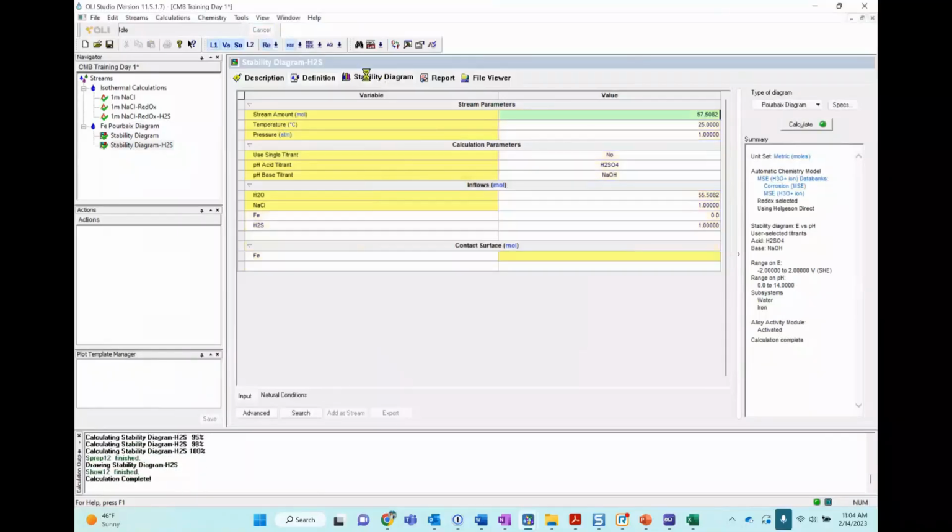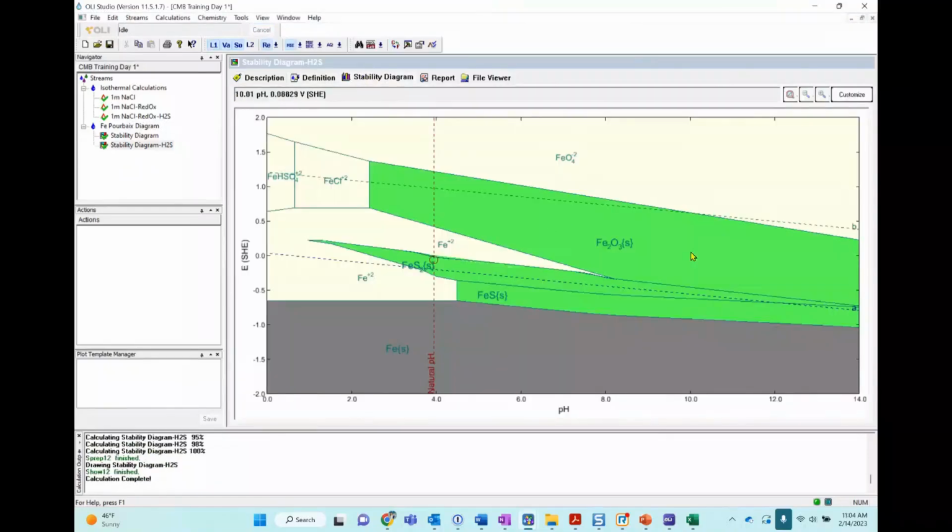And it's very tiny. When you go to the lab and do an analysis in XPS, or not XPS, I forgot, SEM, you'll see that it's a nanometer layer. It's tiny, tiny, tiny, and it has a huge impact on protecting the metallic surface against corrosion. And yeah, you will see a solid layer protecting the metal surface. The other lines that I was showing were just aqueous species that happen to be stable in the aqueous phase. But what we are interested in here is the solid phase.